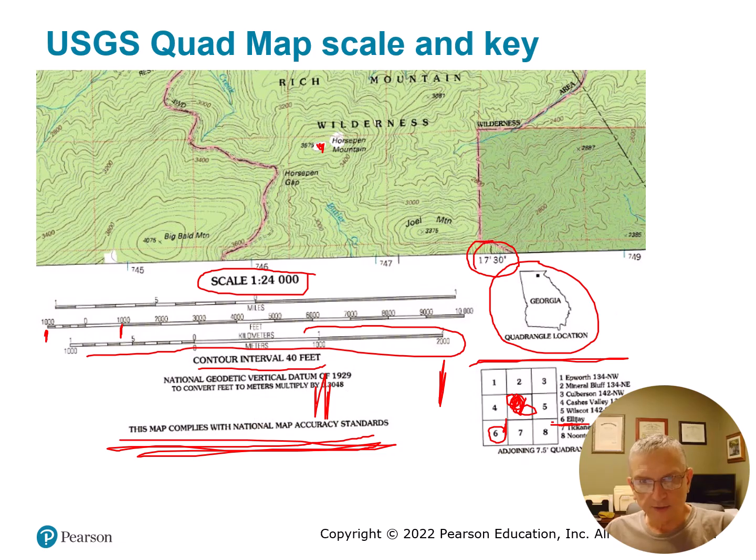And this is 17 degrees, 30 minutes within whichever quadrangle. Quadrangle means that it's 15 minutes, which is a fourth of a degree. So 4 of these quadrangle maps side by side equals 1 degree of longitude and 1 degree of latitude. Thankfully in the US, those are roughly square or rectangular, and we're able to have nice looking square-ish maps.